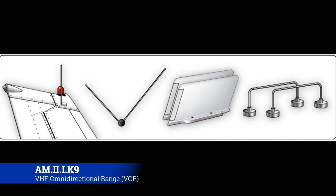You generally won't see those loop antennas. They're definitely out there, and there are some aircraft that have them. As a matter of fact, off the top of my head, I think Chinooks in the Army actually have those. They're just another type of VOR antenna and they work just fine. But being a loop can create some problems, some hazards and stuff like that, so they generally stay away from them. But you could be called on to remove and replace one or troubleshoot one, so just know that VOR antennas can look that way.